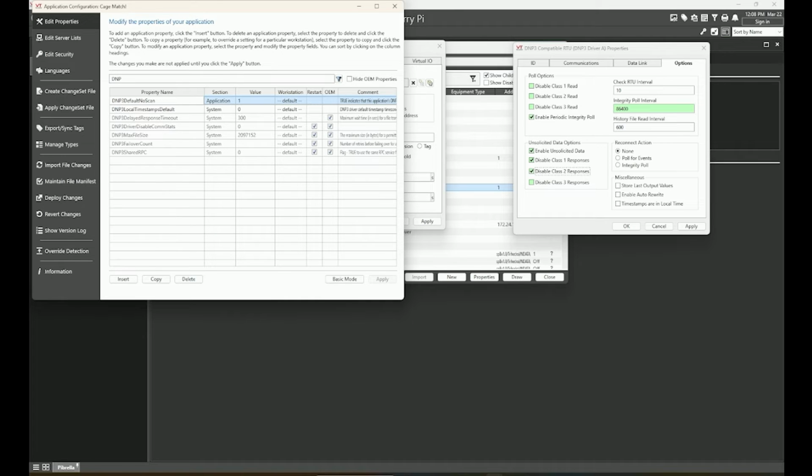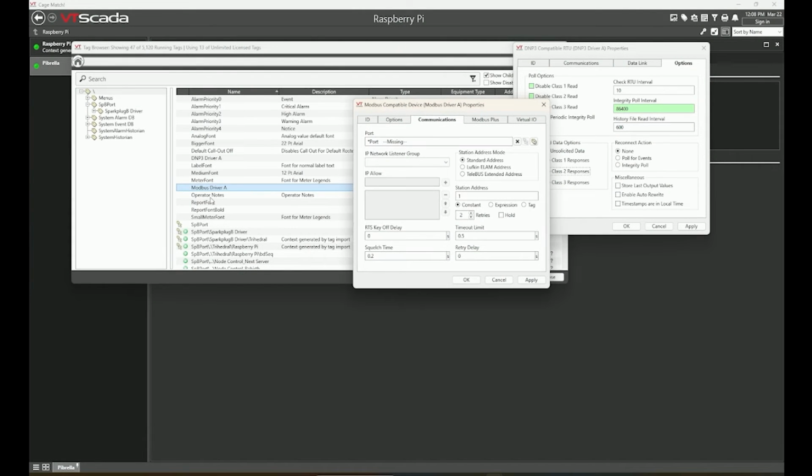If you just type in 30/1/0, it will now default to do no scan instead of direct polling. If you want to have maybe some addresses direct poll, we now have a new address specifier at the end. It's called :DR. Actually, you'll probably see that if I put an IO tag under here.